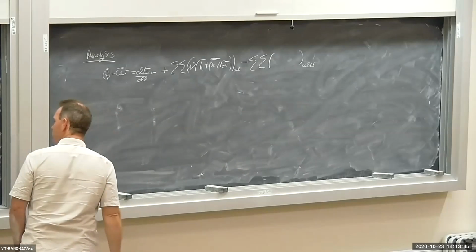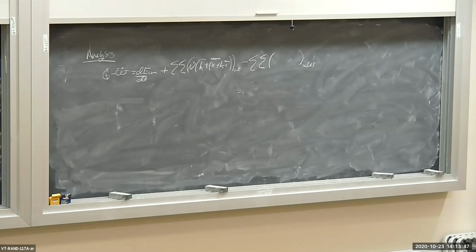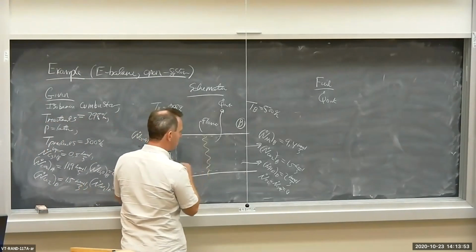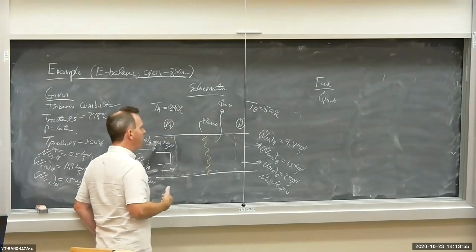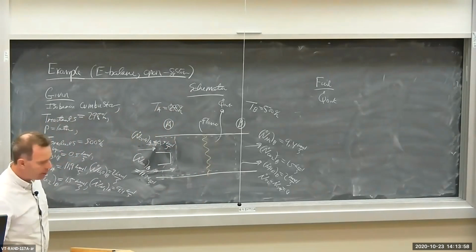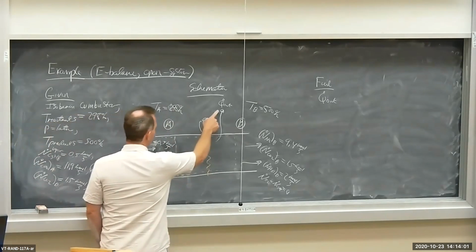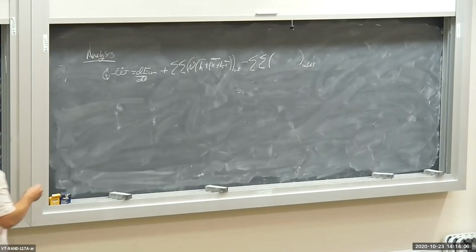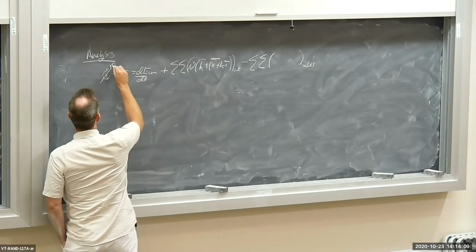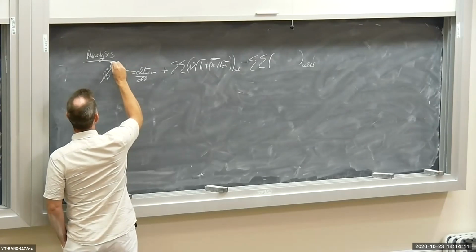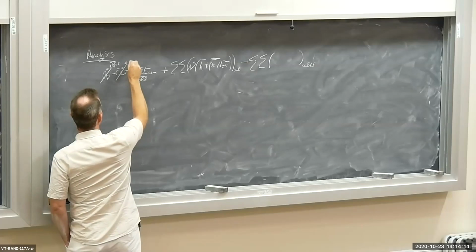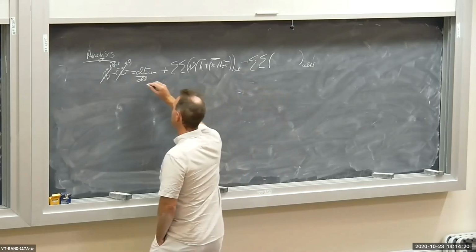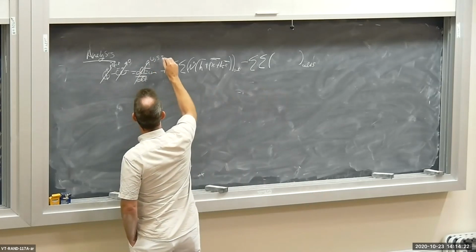Okay, so I don't see any shafts or wires in this combustor. The combustor shape itself is not distorting. The combustor is not being crushed or expanded. So there's no boundary work going on, so there's no work going on here. I have a single heat interaction, which is a Q dot out. So this Q dot becomes a Q dot out. Actually, it's a negative Q dot out. And there's no work, so that's 0. I'm going to assume steady state, nothing else to assume in this problem. So that goes away.